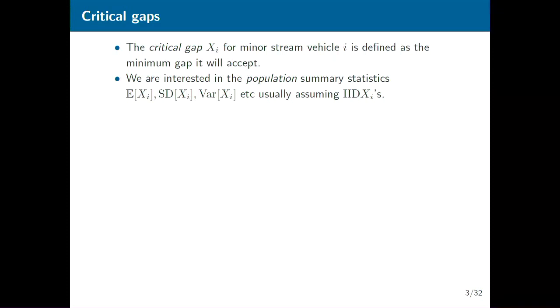In particular, we're interested in estimating the population parameters for the critical gap distribution, usually assuming independent, identically distributed critical gaps. So you're not really interested in the critical gaps of specific drivers. You're also not really interested in, say, the mean of the 200 drivers that were in your data set, but the mean critical gap of the whole population of drivers.